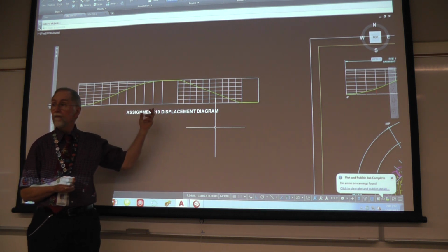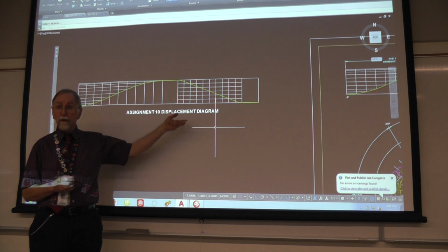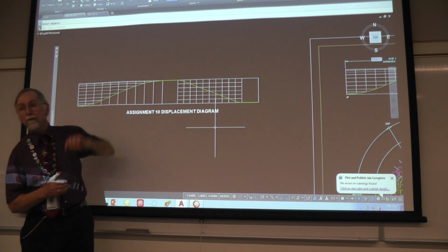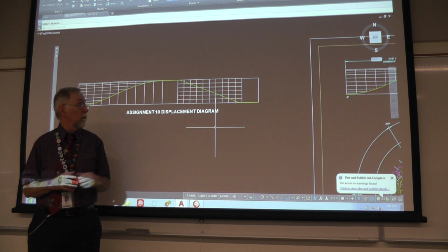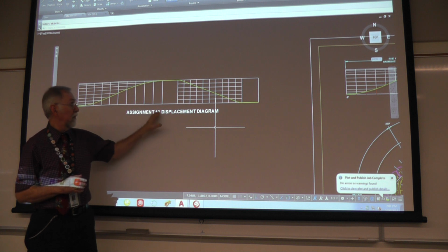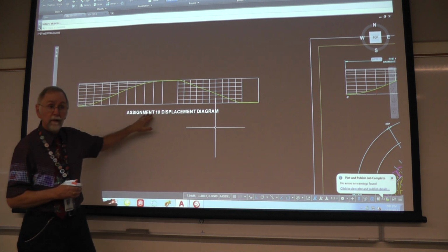The reason it came in with hidden center lines in it is because that's the layer that was current at the time that I brought it in. If layer 0 had been current, it would have looked more like this. Exploding it will allow you to get rid of this.